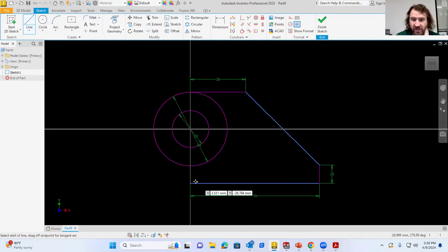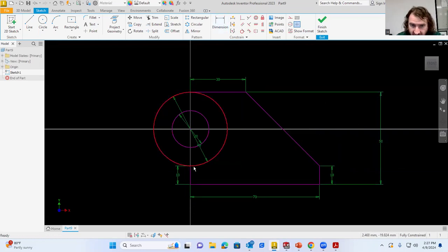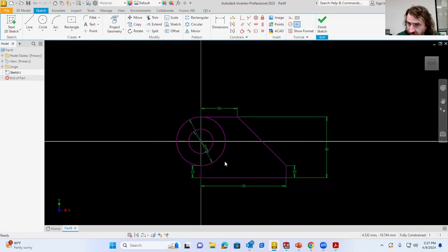And then of course we can finish this by drawing the 10 mm line that is going to be right here. So 10. And there we are. We just want to make sure that this is correct here. So from this to this should be 50. There it is. Now we're cooking. Now we're good because now there's a connection there, and we got a fully constrained sketch.